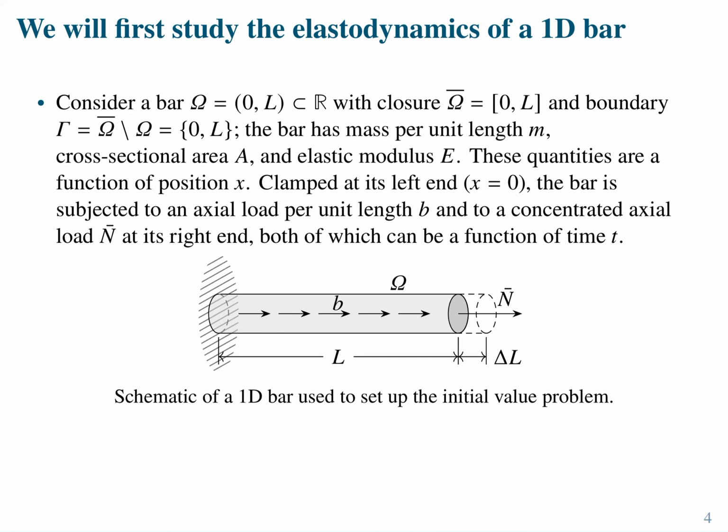So in the very beginning, I said we're going to start with a bar. It's basically the simplest mechanical element that you can think of, right? It's a structural element that can sustain only an axial force, so you can have the bar in tension or compression. It cannot get simpler than this, okay? But we start from here because everything that we do in higher dimensions is really analogous to what we're going to do in 1D.